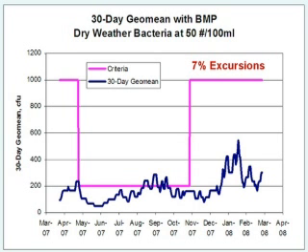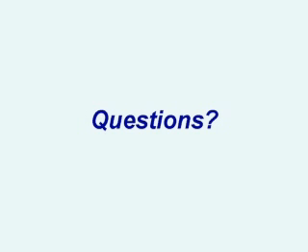We have a dry weather bacteria problem, and we're looking at the rolling average geometric mean in that creek. This is in-stream loadings, and it exceeds the standard, or there are 52% excursions in a given year, pretty much all during the summer. The wet weather loads are still high, but this is after the BMP, with no treatment of the dry weather flow.